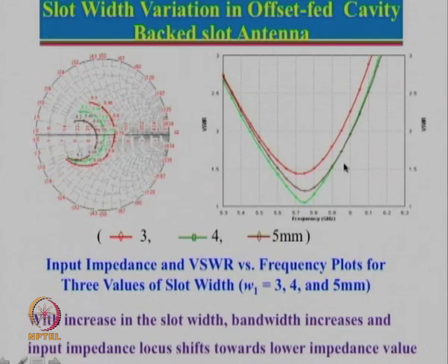So, you might start wondering, what is that? Why has bandwidth not increased? Well, the reason for that is that impedance is not matched properly. So, we need to do something so that we can do a better matching for this particular width. If it is properly matched, then this curve will shift to this side, and then this is the VSWR equal to 2 circle.